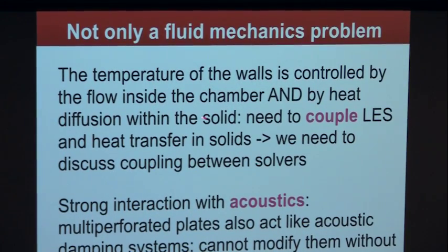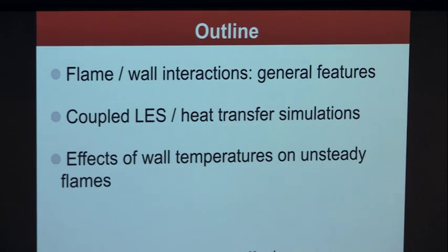Even for a smooth wall, actually, someone asked me the question 5 minutes ago, you still have the problem that if you do the computation of a chamber, you need to specify wall temperature. How do you get the wall temperature? Well, someone can give it to you. If you don't have it, the only solution is to solve for the temperature in the wall. So you do a coupled heat transfer simulation. And you need to discuss then how you couple the solvers: the LES solver in the chamber, and then the heat transfer solver outside of the chamber. And the acoustics I've mentioned before.